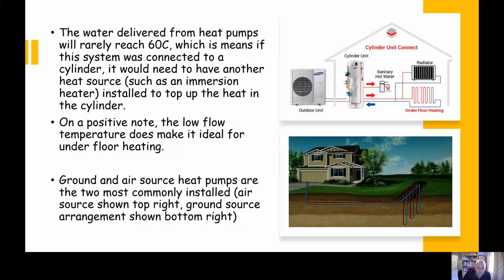It has got quite a low temperature that it releases, which makes it good for underfloor heating. Not so good for traditional radiators. You'd need to oversize traditional radiators because you wouldn't have as much heat going into them, so they can't transfer as much of that heat to the room.